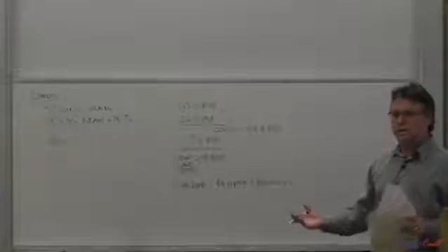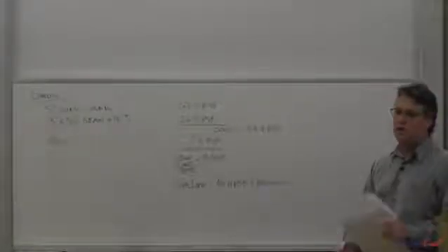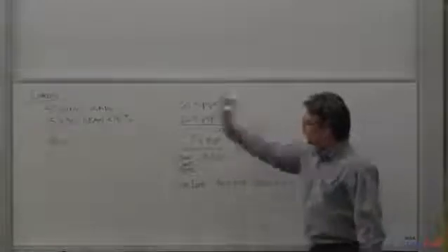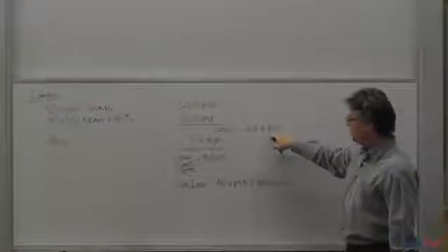Then when you go to design this column, you know what the beams weigh in pounds per square foot. You know what the girders weigh in pounds per square foot. You know what the column itself weighs in pounds per square foot. To get the dead load on it, you just multiply the tributary area by the pounds per square foot of everything framing to it, and you will get that number. It's a very easy way to keep track and keep things flowing in your design calculations. So the concrete only part of this, just the concrete weight itself, is 89.4 pounds per square foot.